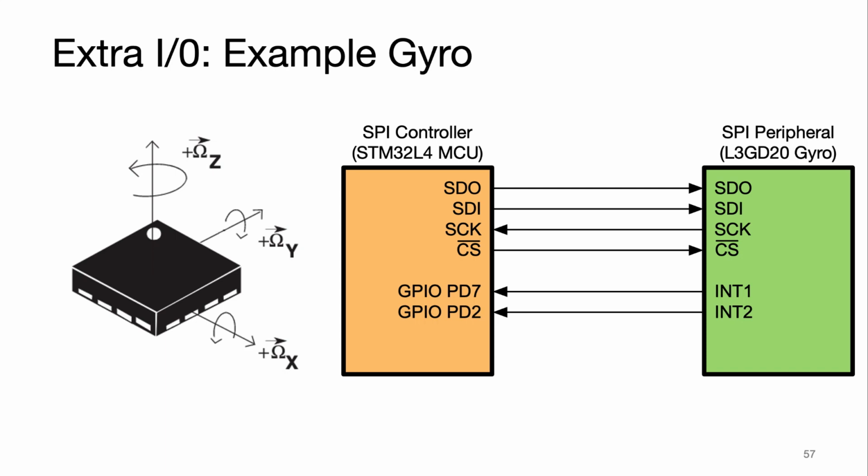The other one that's often tricky is that say you have a couple of dedicated chip select lines built into the drivers or the module for the microcontroller you're building or using, but you need an extra one. You want all your drivers to already work and know when to pull chip select low, but you need this extra line. So oftentimes you have to dig into the firmware libraries to add in an extra chip select. Say the standard number of peripherals is 3 for your chip, and then you want to make it a 4th. It's totally possible. You just need the serial peripheral module to be pulling that line up and down for you at the right time. Okay.